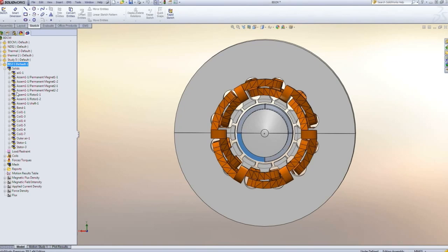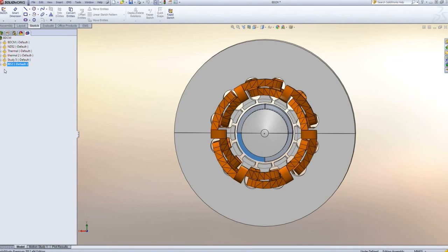And EMS will automatically now run only this study, using those parameters, and then I'll be able to actually compare results. Now I can also do something else. I can make a few modifications, whatever I want to make, and then I come here and say run all studies. So if I'm trying to optimize and sweep something, I can use that feature right there.